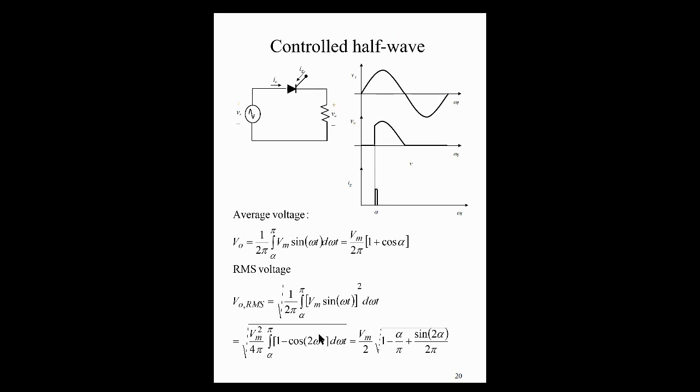When we look at just the resistive type load, we observe that there was no difference between the output voltage and current waveform, no phase shift, and this is quite expected. We then looked at how we can determine the average output voltage and current, the RMS voltage and current in the resistive type load.